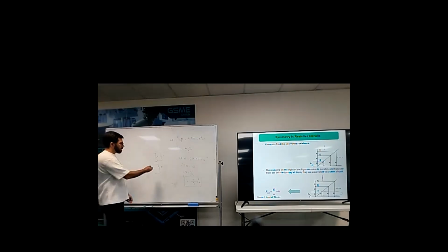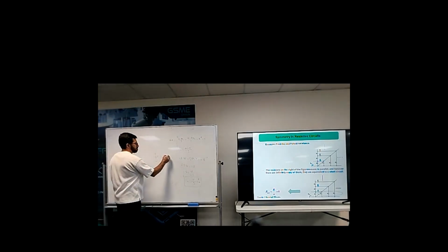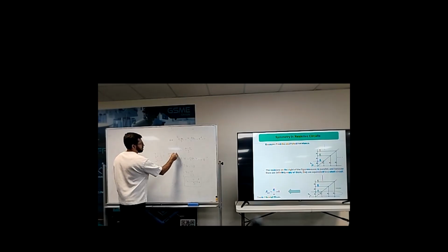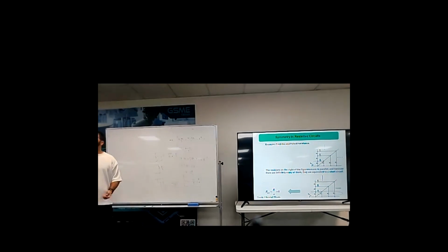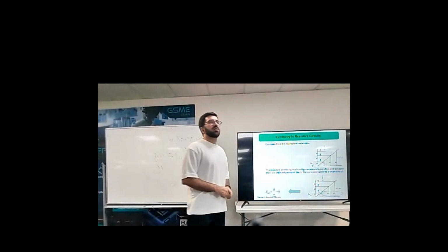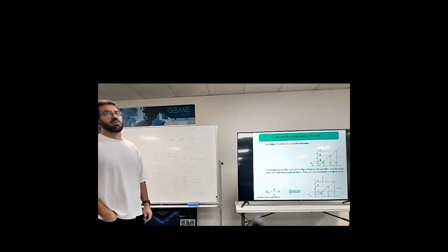How do you calculate them? Multiply them over the sum of them, yeah? If you have 3, how much is the equivalent? R over 3. If you have 10, it should be R over 10. If you have an unlimited number of resistors, it should be 0, which means that's only wire, yeah? They are short circuited. So you can consider this side as a short circuit.